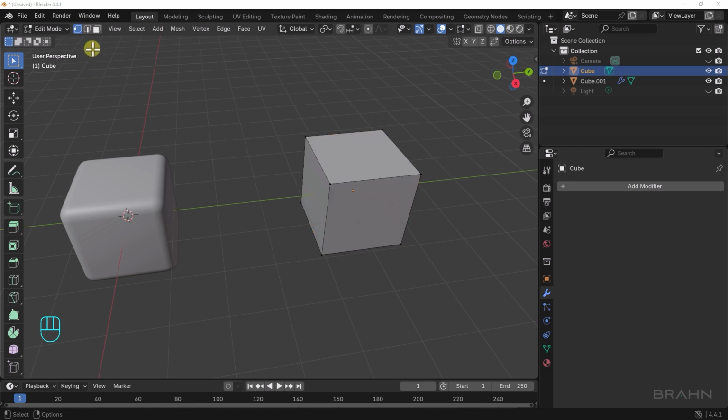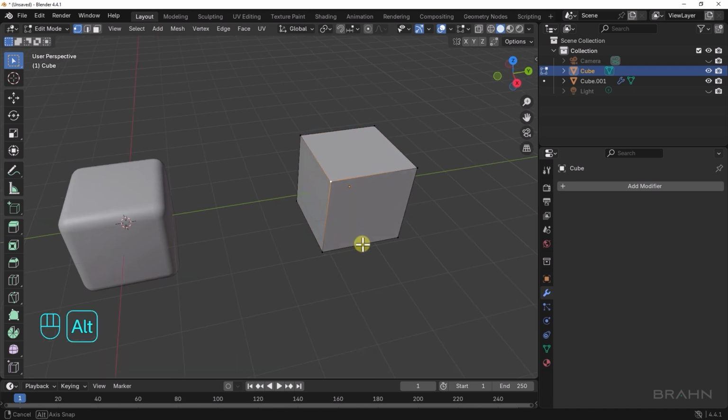Across the top next to the Edit Mode drop-down are 3 little icons. These represent a select mode of vertex, edge, or face depending on which one you want to work with. Click on the first one, if not already selected, and you will notice the little vertices show up in black on your original cube. Click on one to select it, or click drag to marquee select one or more of the vertices. I'm going to select the one closest to me.